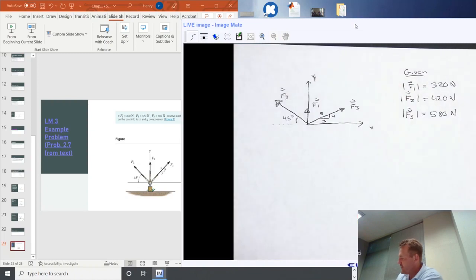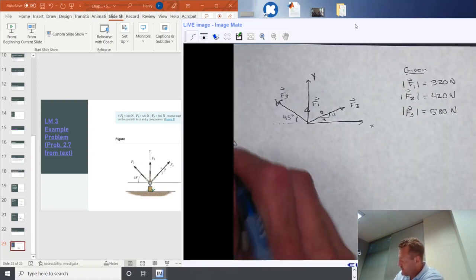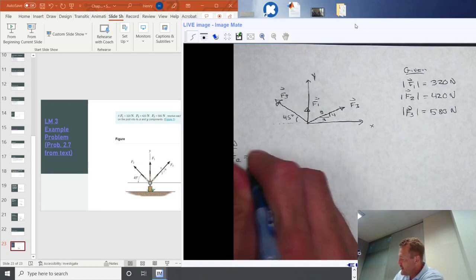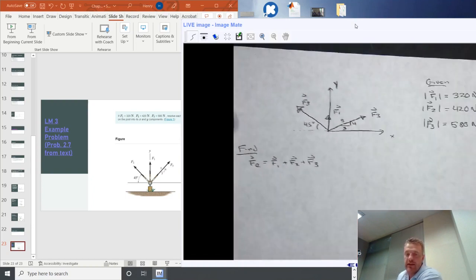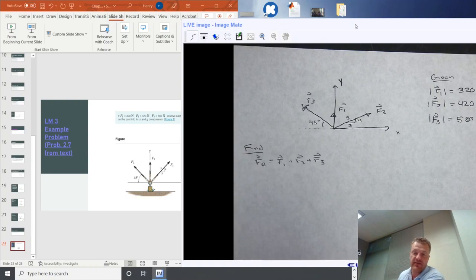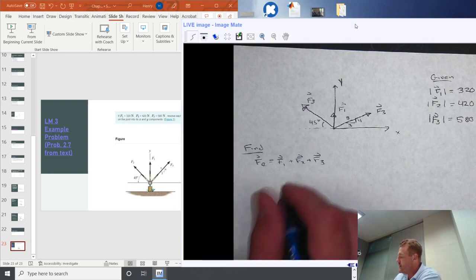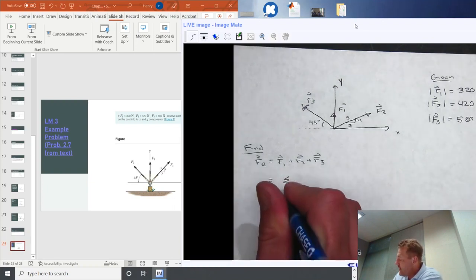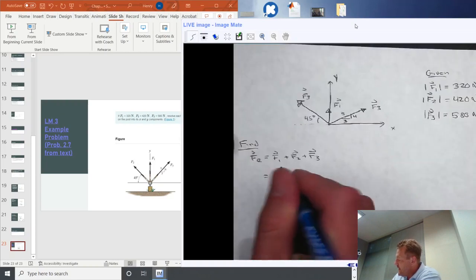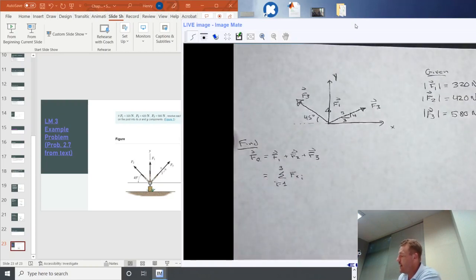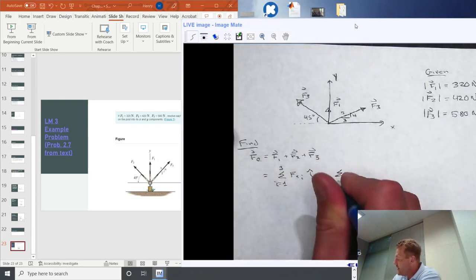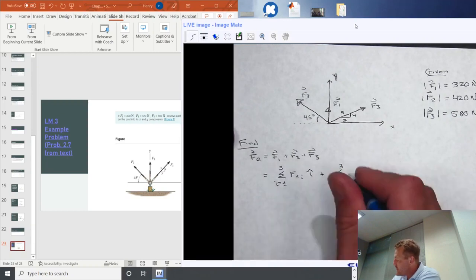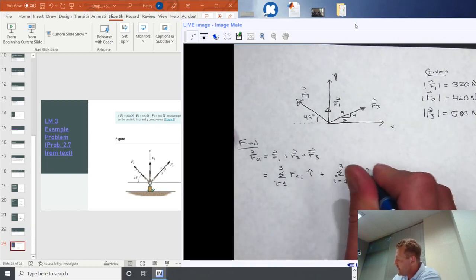Here is our y-axis, and we're asked to find the resultant force vector. So remember that the resultant force vector is nothing more than the vector sum of those three forces. And I could take a geometrical approach. I could draw these according to scale and arrange them according to the parallelogram or the triangle rule and attempt to take that approach. However, we know that it's just going to be easier to add, from i equals 1 to 3, all of the x components of those three vectors, times i hat, plus the sum of all the y components. And I will write that as a vector by scaling it by j hat.